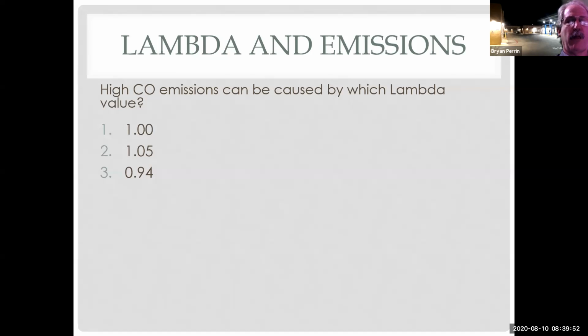So it's truly all about fuel control first. And until fuel control is working correctly, nothing else is going to operate efficiently. So I do this because, again, we're used to thinking rich and lean. I want you guys thinking about lambda and how lambda affects emissions.